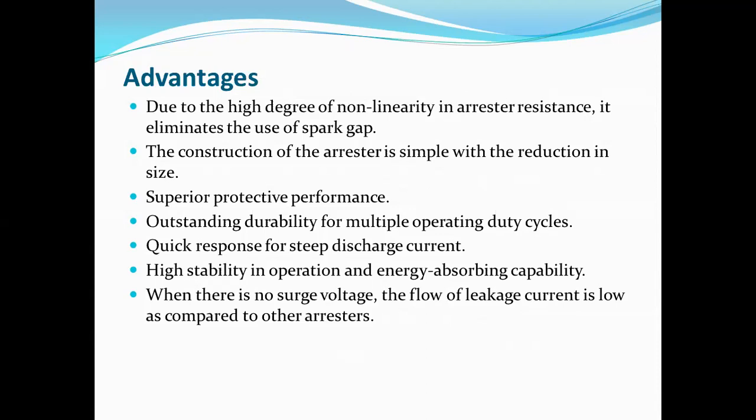Superior protective performance means what? Means under normal operating conditions, it will have a very high resistance. Under faulty conditions, immediately its resistance decreases, and again it will regain its normal working condition. That is, again that resistance will increase, for the normal operating voltage.